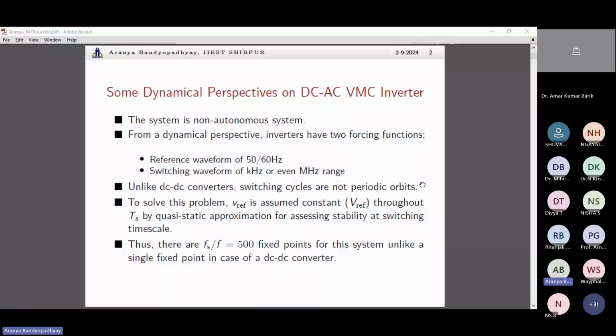The modulating waveform is either directly a state space variable or a function of the state space variable. And whenever it encounters an edge of the carrier waveform, a switching will happen. At that exact point, a state switching will occur.